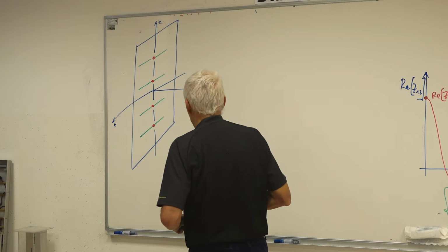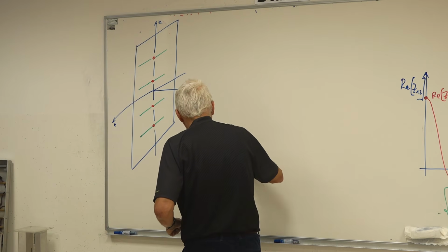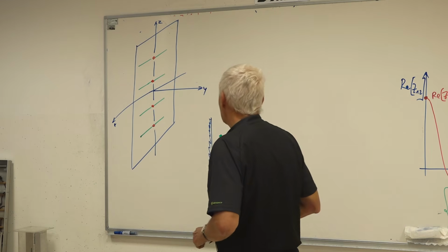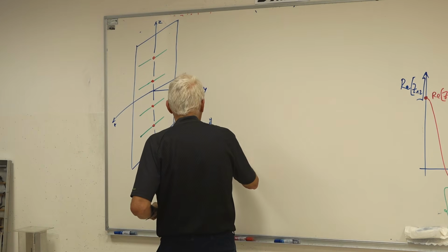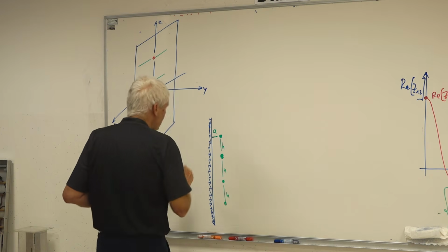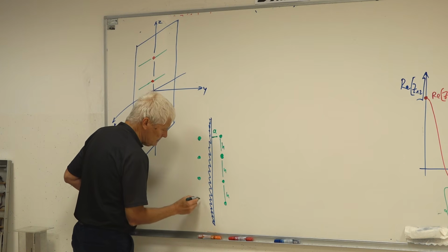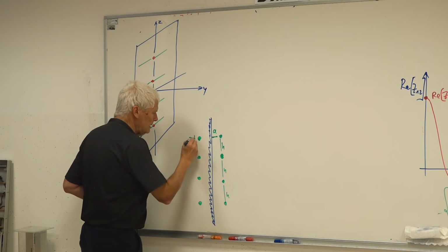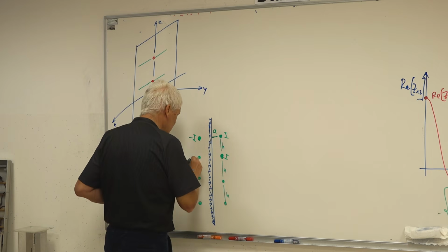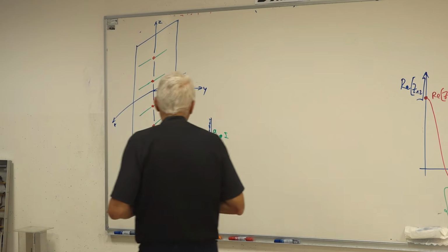I should see what the spacing is. So, let the spacing between the dipoles be h. Here, h, h. And let the spacing of the dipoles from the screen be a. Of course, I have the mirror image of this antenna array inside the big metal screen that has minus I, the current. It's a broadside array, all dipoles are fed in phase, but I have minus I in the screen, and I also have distance a here.